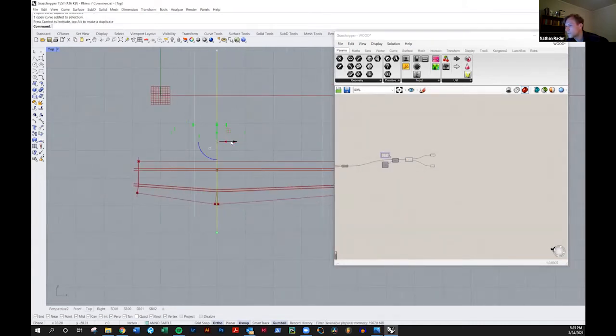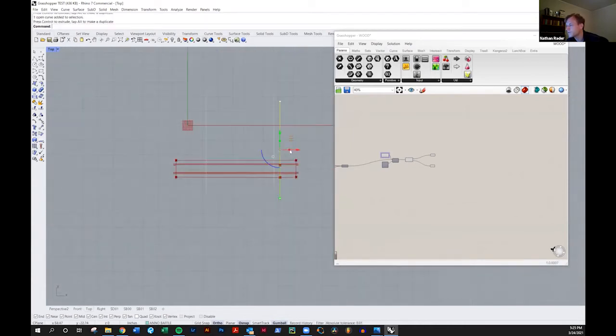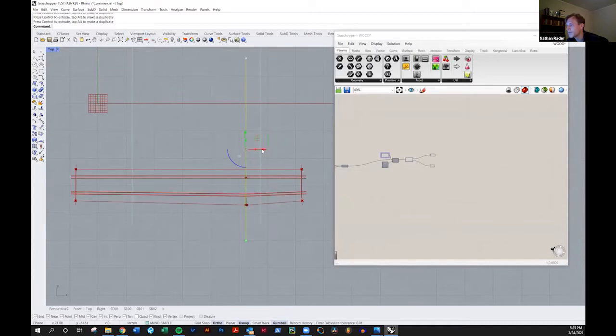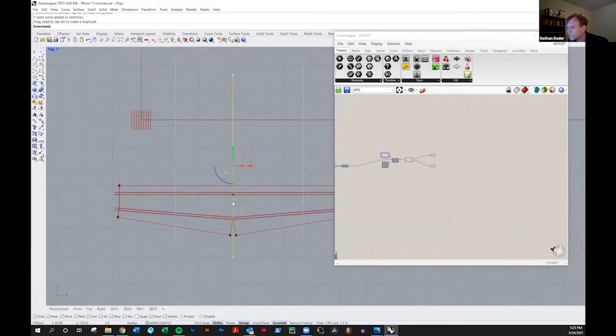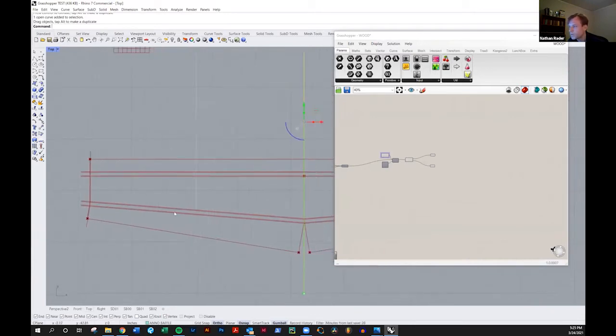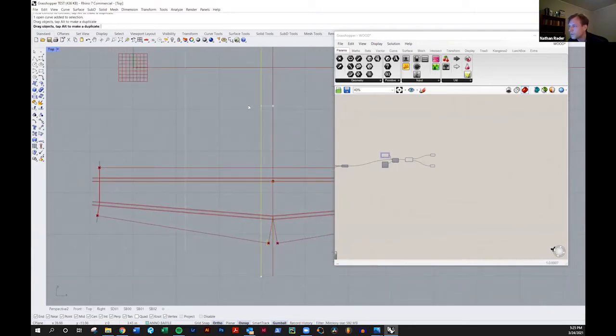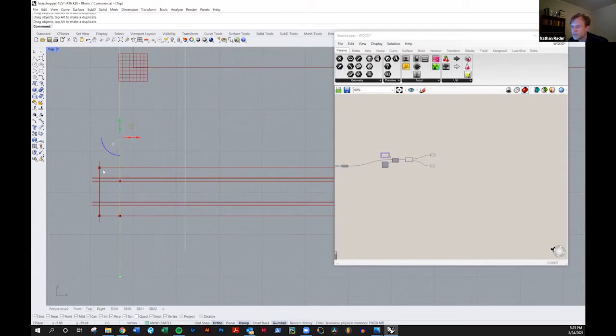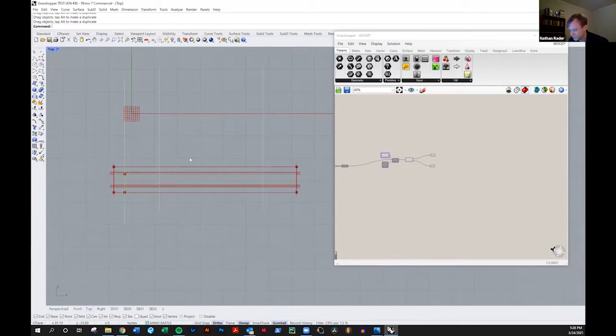Basically with this one, I can just move this part around and it follows a cosine function so that I can have an array of baffles in a ceiling swell and undulate. And I can just move this center line. The reason I did a cosine function is because these edges pop out on the corners more when it's deepest. So I wanted that to reduce as I get towards the end, because otherwise I would be running off a sheet of material.